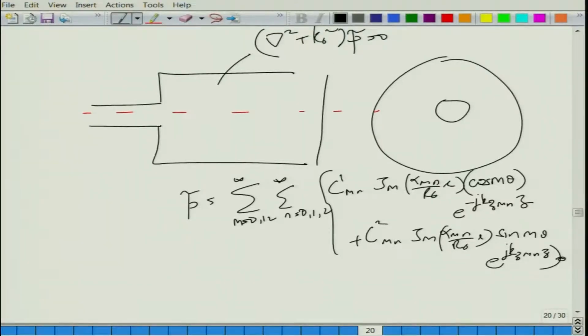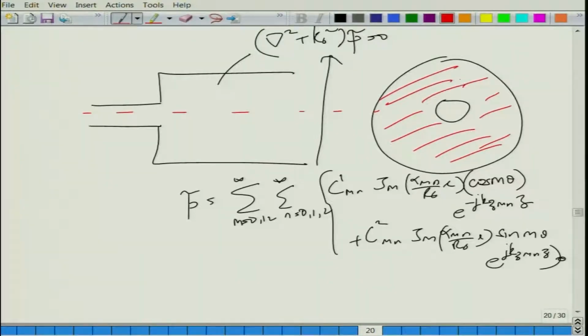The solution of this is a solution of this equation, there is no source term here. But what happens really, over the annular surface where I have shown with the red hashed surface, velocity u z is 0, and u naught, let us assume you are assuming a uniform piston driven model here. So, it is u naught. So, u naught is equal to u z, which is non-zero. Okay. And in this port, immediately from the port chamber interface you can assume planar wave.